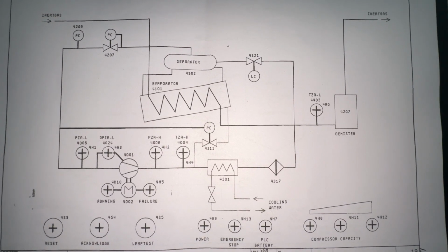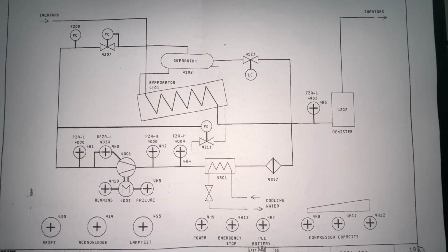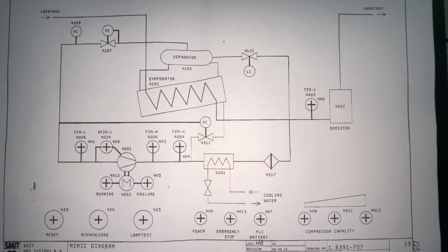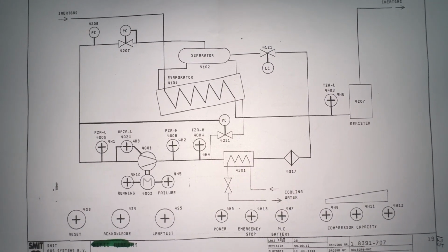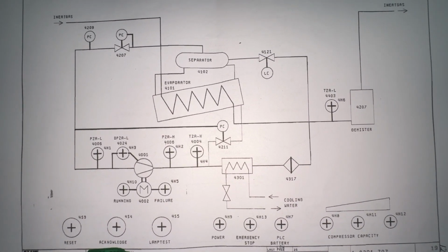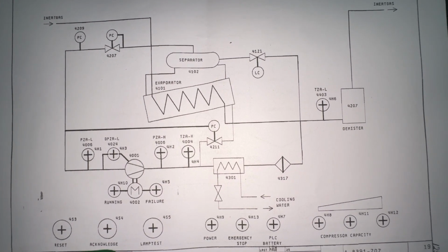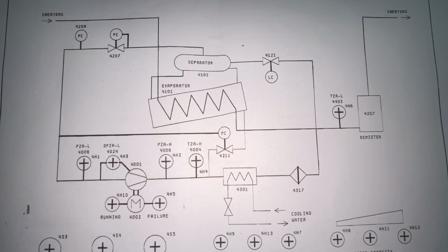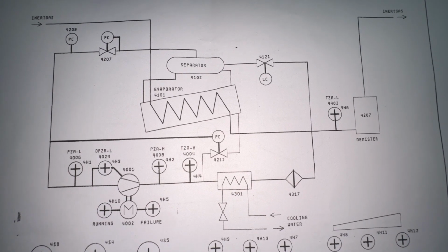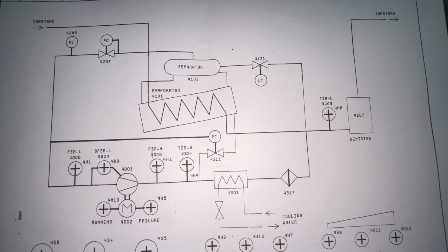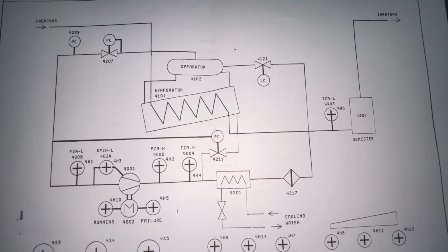So as I said in my previous video, the inert gas from the inert gas generator will come to the chiller plant, and this is the mimic diagram of the chiller plant. This IG coming into the chiller plant is clean with oxygen of 1%. But as we made IG in ambient air, that is atmospheric air, in the inert gas generator at room temperature,